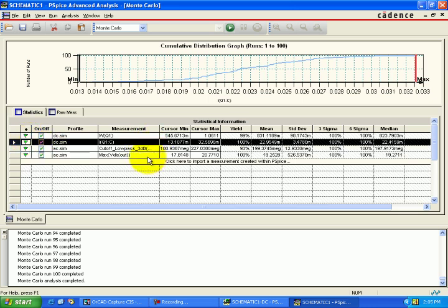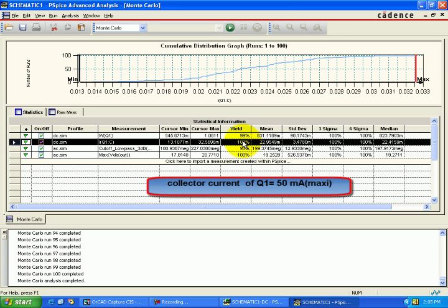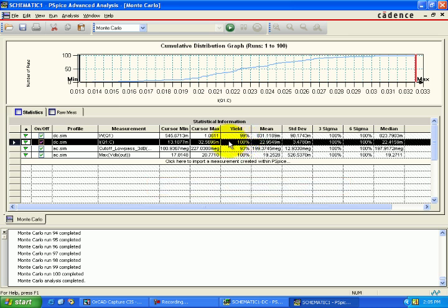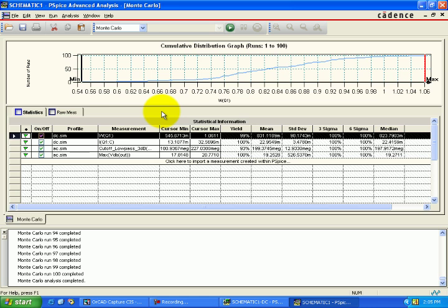All the changes we did, like changing R3 to 5k, were because we needed to increase that resistance in order to make our circuit function well. So this is all the Monte Carlo's magic, in order to know which particular component will affect the percentage yield, or getting satisfactory results for our main graphs, our main design parameters, and our design circuits.